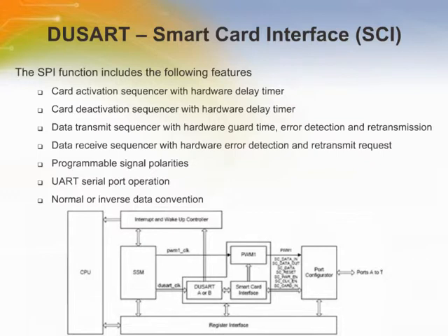The Smart Card Interface module contains all of the logic functionality required of the terminal or controller part of the Smart Card interface. Activation and deactivation sequences are supported with various degrees of automation. Protocol type T=0 is supported. Refer to the Smart Card standard ISO 7816 parts 1 through 10.